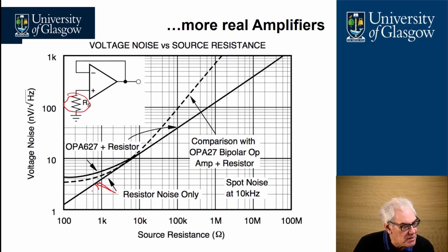So we can check this quite simply to see if it's correct, and we find that a 1 kΩ resistor here gives us about 4 nV/√Hz, which we know from previous calculations is exactly right, because a 1 kΩ resistor generates a noise power spectral density of about 4 nV/√Hz. And similarly, if we move up to 100k, we discover that it measures 40 nV/√Hz.